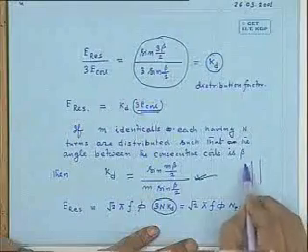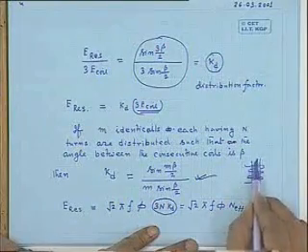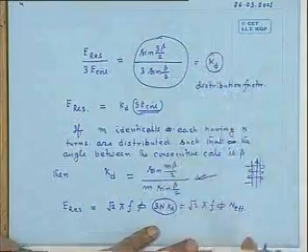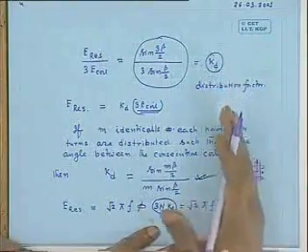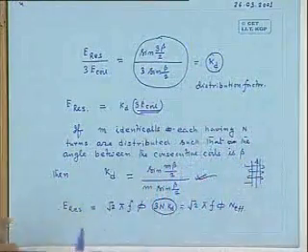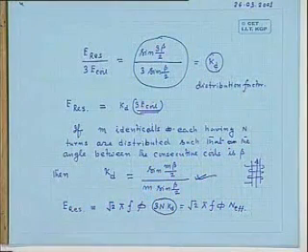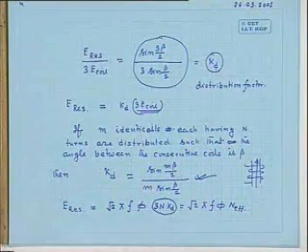In case of a transformer, there was no problem. In the transformer, this was the limb, and all the turns were linking the flux in the same phase, d phi dt the same for all of them. There was no question of distribution. But here in a rotating machine, if you want to utilize the whole periphery of the machine, you have to put conductors.